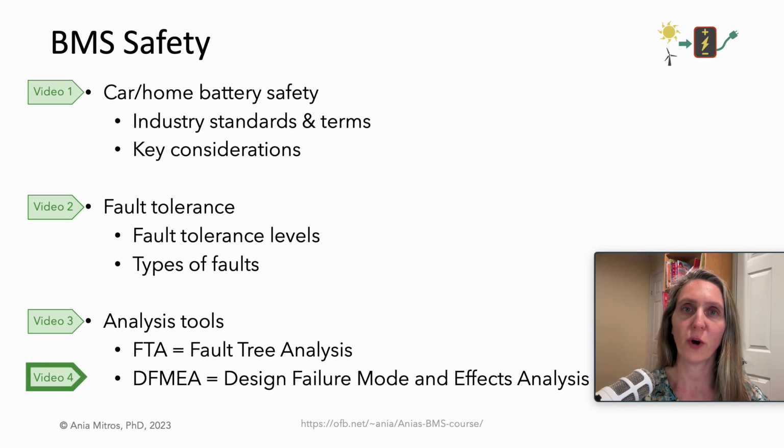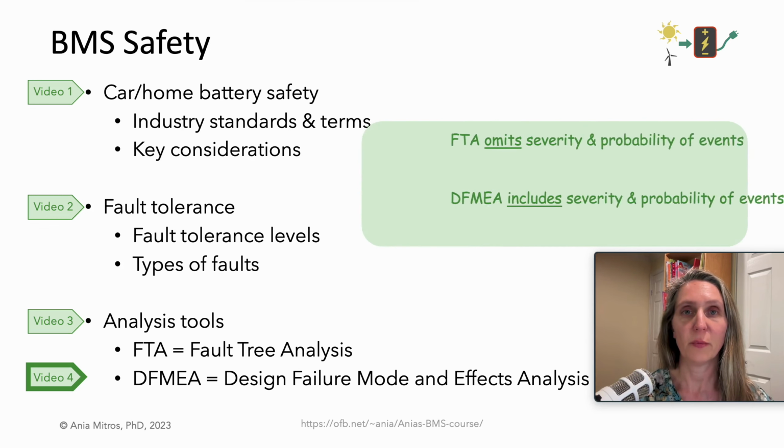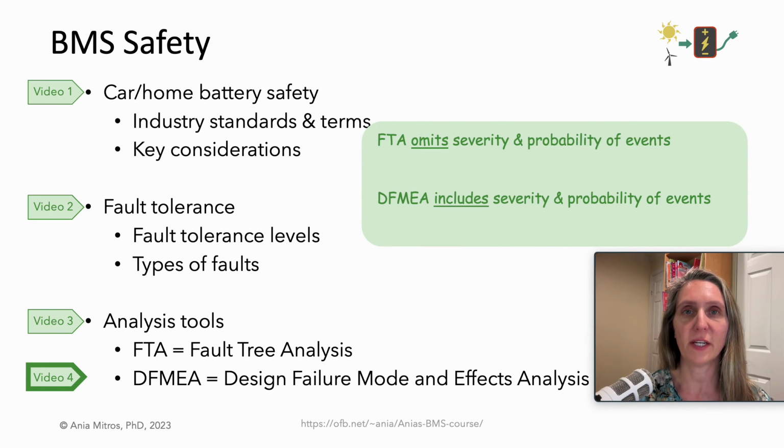This is video 4 in the lecture on BMS safety. In this video, we'll discuss DFMEA, or Design Failure Mode and Effects Analysis. An important difference between FTA and DFMEA is that fault trees omit the severity and probability of events, while DFMEA includes these assessments.